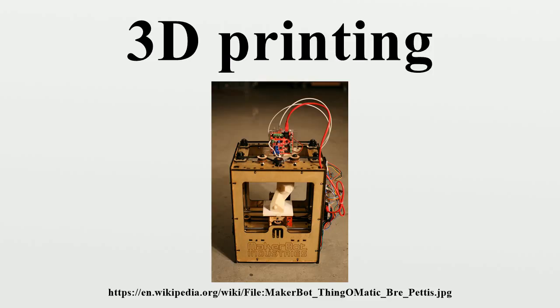Selective laser sintering was developed and patented by Dr. Carl Deckard and Dr. Joseph Beeman at the University of Texas at Austin in the mid-1980s, under sponsorship of DARPA. A similar process was patented without being commercialized by R.F. Householder in 1979. Selective laser melting does not use sintering for the fusion of powder granules but will completely melt the powder using a high-energy laser to create fully dense materials in a layer-wise method that has mechanical properties similar to those of conventional manufactured metals.